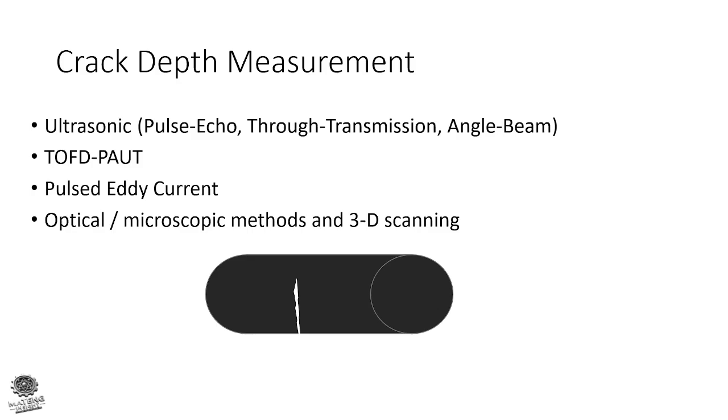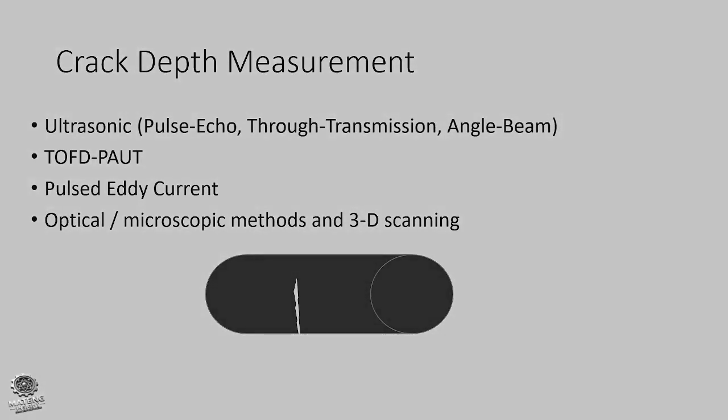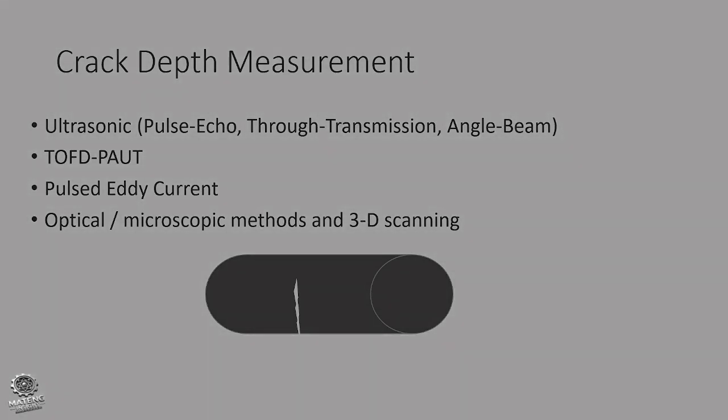Accuracy depends on material properties, geometry, crack orientation, probe frequency, and test setup. Combining multiple techniques, for example, TOFD plus PAUT, often yields the most reliable sizing.